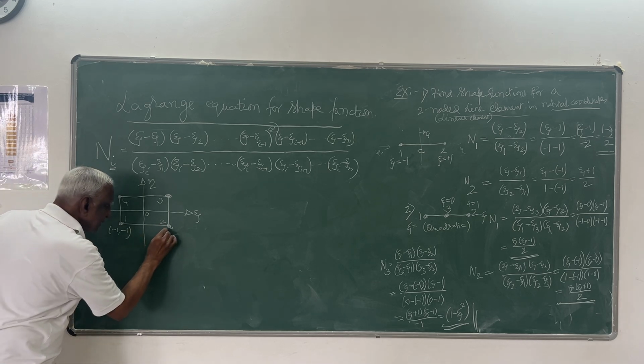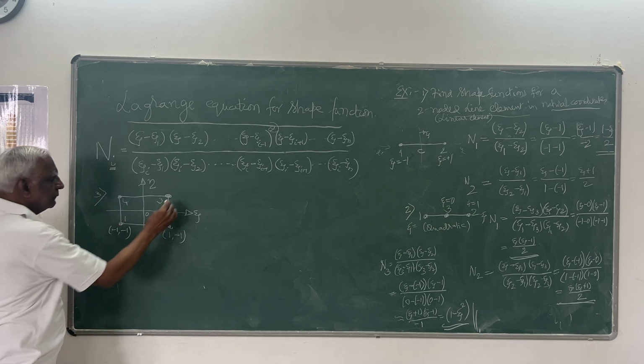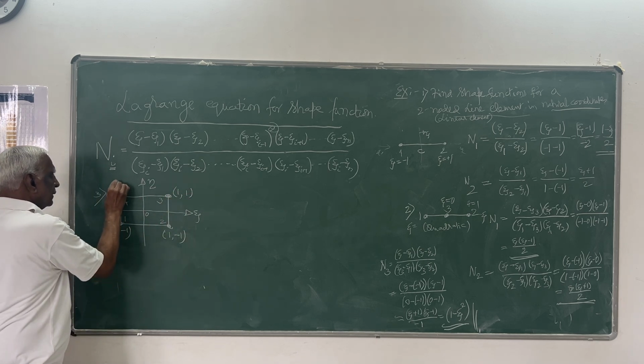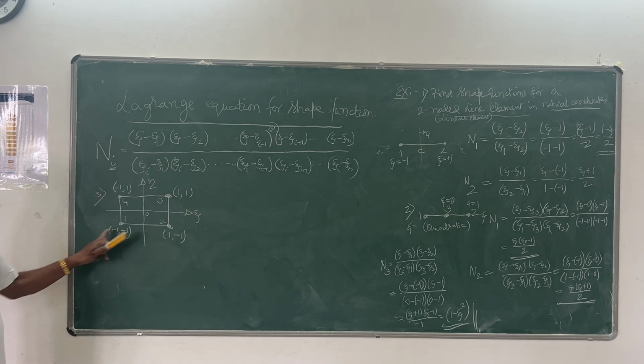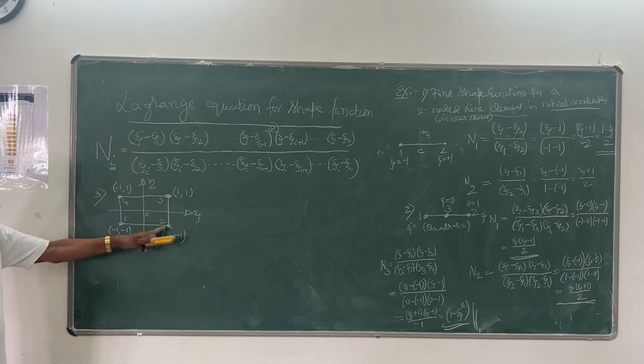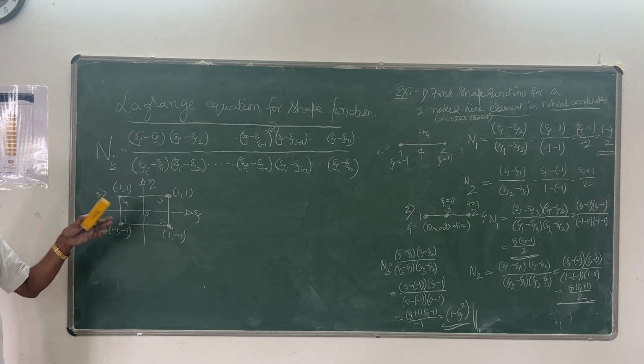So here, this coordinate, it is 1, minus 1, 1, 1, minus 1. X, Y coordinate, or psi, eta coordinate. Parent element, or it is natural element, primary element, having nodes only at the corners, not higher order, first order, basic finite element for useful two-dimensional analysis.